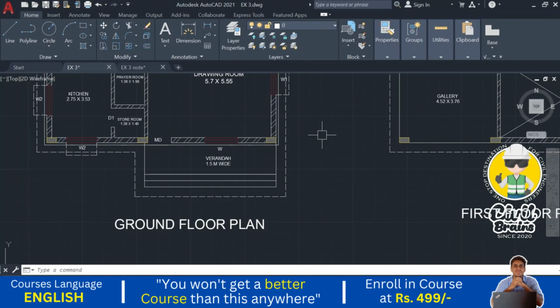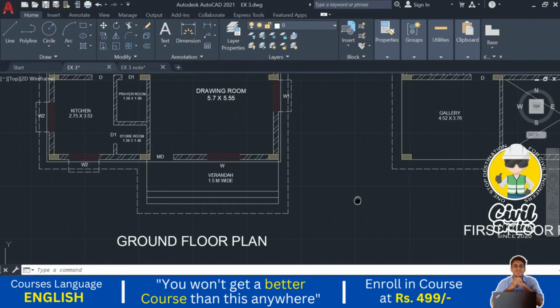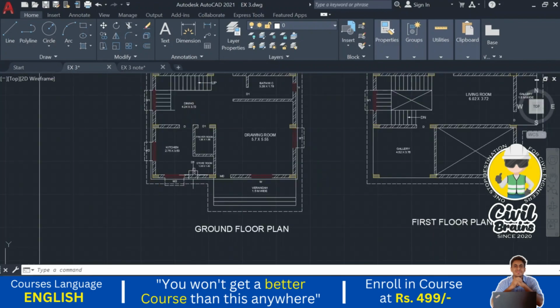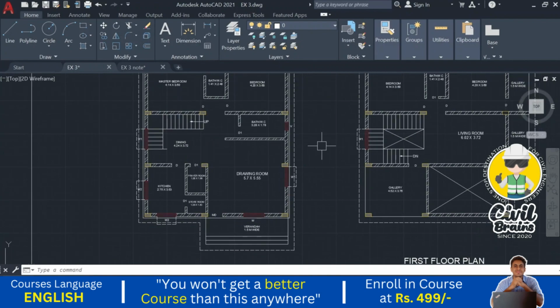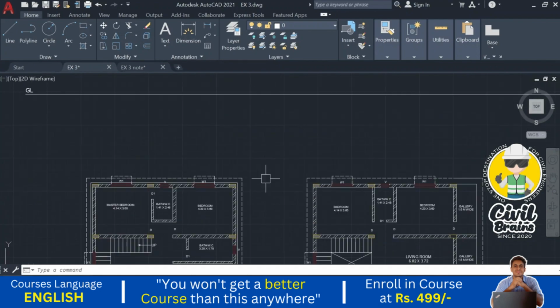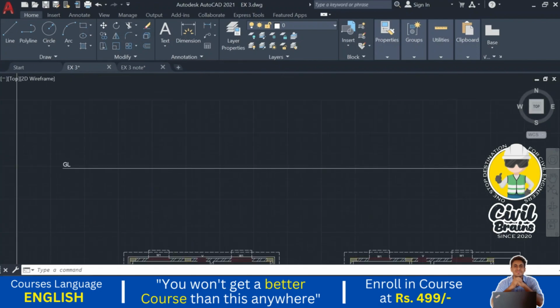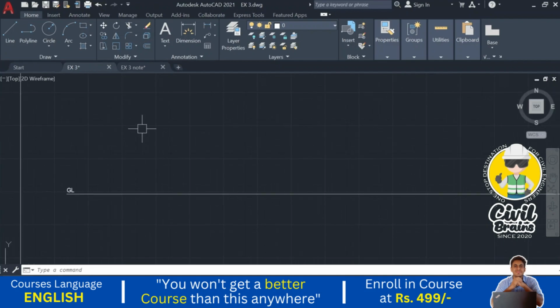Okay, so doing the front elevation is a little easier, because we only need to project these lines. Whatever the front elevation lines will be, those we need to project, and we should know that in the front elevation the important thing is the levels. What is the ground level, what is the plinth level, what is the sill level, what is the lintel level, what is the slab level, what is the parapet level. Okay, so those levels we need to show first. We just show those levels quickly. Once we are done with the levels, according to the projection, we cut down all the things.